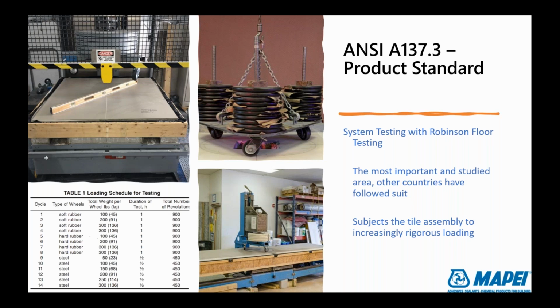And what happens is we put a gypsum bedding down here, then a 4-inch concrete slab, and we set our tile to it, again, with a polymer modified mortar. Or in this case, I put another panel together exactly like this, but I also put a 5 millimeter recycled rubber membrane in there. And then we run this test, very consistent. In our case, we use a universal machine, as you see here on the left, and it comes down from the top and applies weights.